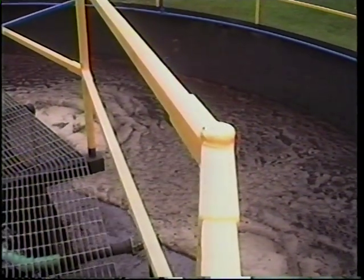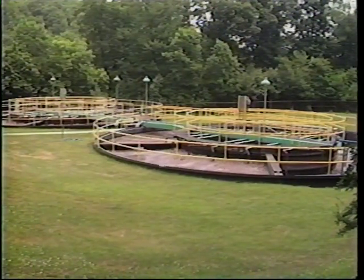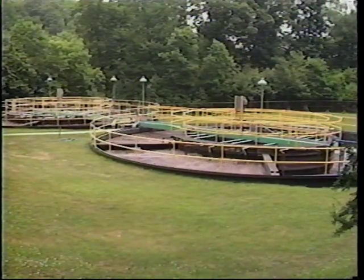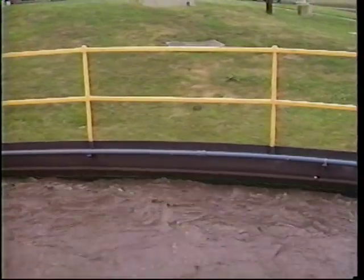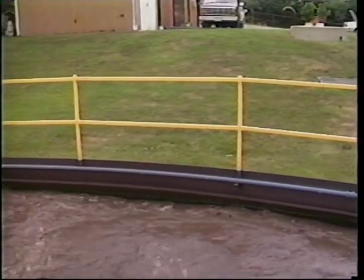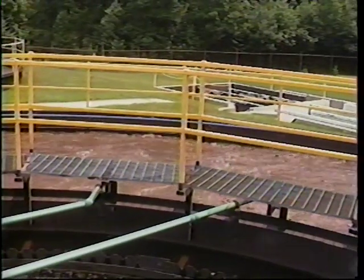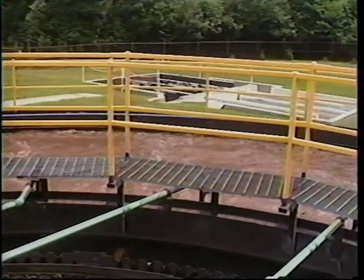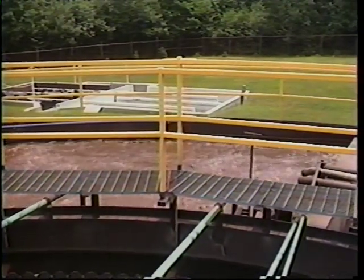The contact stabilization activated sludge process is different from the conventional activated sludge facility and usually utilizes two connected aeration tanks. In the first tank, known as the contact tank, the influent wastewater is introduced to the hungry microorganisms where a process known as adsorption takes place. The wastewater usually spends 30 to 60 minutes in the contact tank where the hungry microorganisms become attached to the food in the wastewater. The wastewater then passes into the clarifier where the microorganisms settle out and are returned or wasted. The returned sludge is not returned to the contact tank.